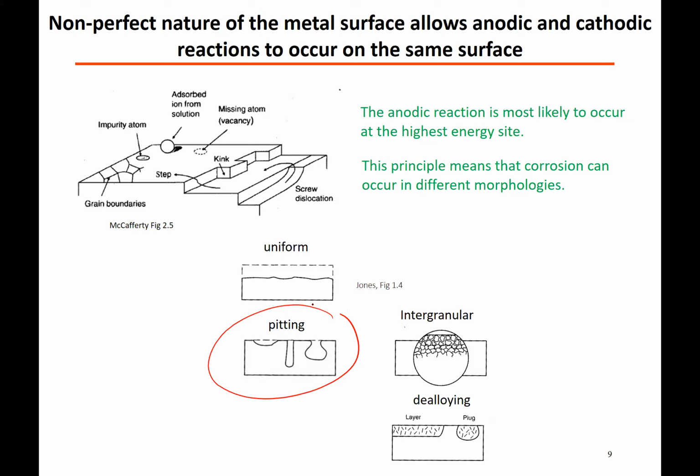So that's granular corrosion. There can also be some de-alloying here. Or sorry, they can be in between the grains. And what that means is the electrolyte can come in and seep along the grain boundaries where the imperfections are. Right, and we talked about how when you have de-alloying, it results in all these non-uniform pits.